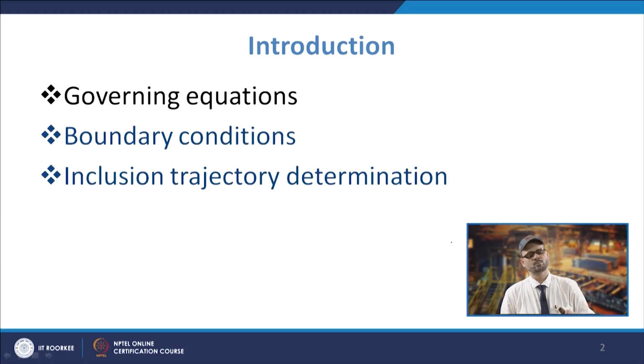You must also know the different kinds of boundary conditions. We saw that we have the governing equations, and we also have the boundary conditions. There are different types of boundary conditions on these discrete phases which we use. You may have a boundary condition for trapping, or a reflection boundary condition, where depending upon elastic or inelastic collision they will be reflected.